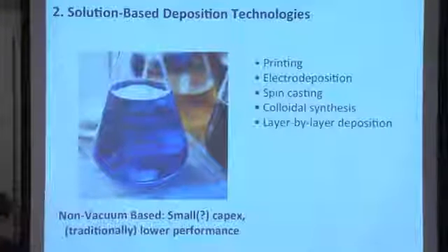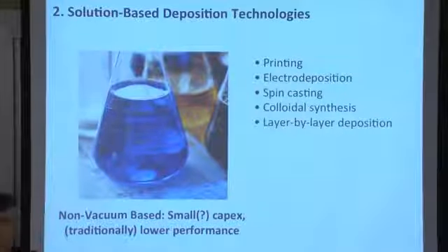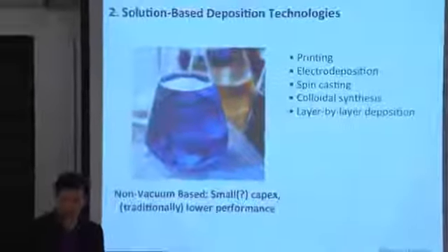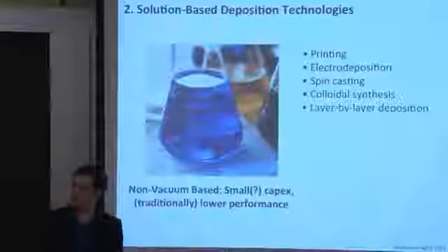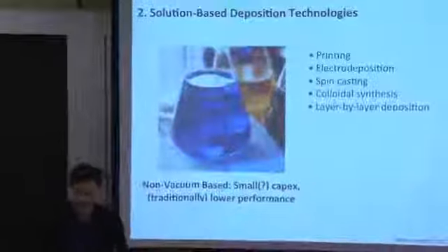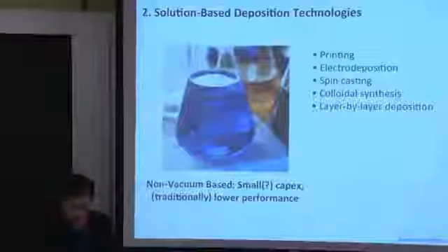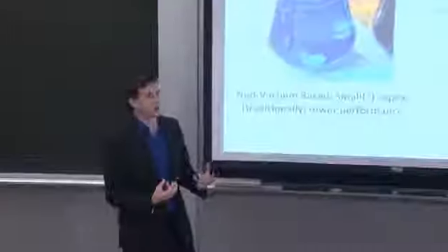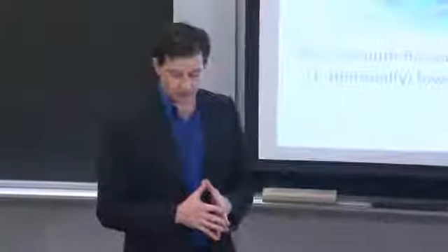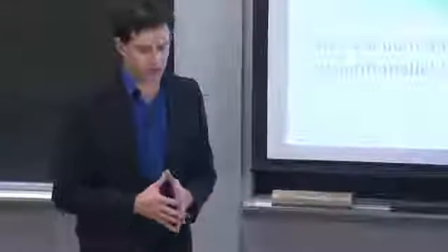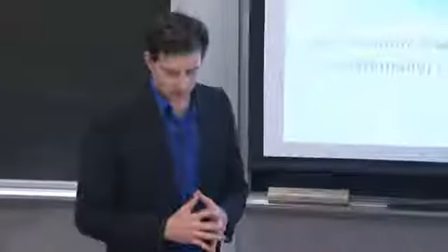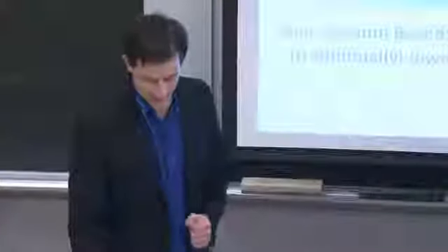Electrodeposition, on the other hand, is fairly well known. You're, again, applying a voltage difference between two electrodes, one of which will be your substrate, and depositing species contained within your electrolytic solution onto that substrate, growing your layers. Because you're growing at room temperature, these films tend to have rough surfaces. That could be a downside of electrodeposition. They might have some pinholes as well, but you do get fairly large-grained materials. It can be a very gentle growth process. And of course, the advantage is lower temperature.